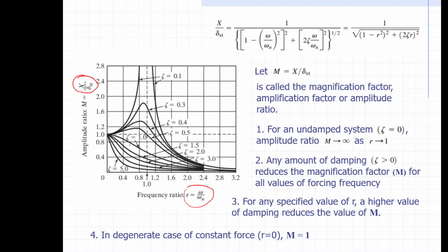And with higher damping ratio, the system is not moving fast, because a higher damping ratio means the damper is very strong. So if the force is at a low frequency, it does not disturb it so much. It does not vibrate so much. Okay, you just try to visualize this and get the insight of this graph explanation.